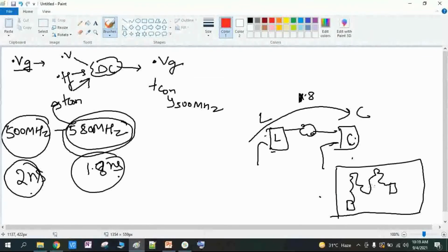What this transition time is, we will discuss later on, but understand the tool tries to improve this net. Think in this way. Let's say to improve this net, the only thing which can improve it is a buffer. I can add a buffer. Right now don't think how it works, that will be taught here. The only thing I'm telling is that to improve the bad feature of this net, I can use a buffer. So for this high detour, I need to use some buffers. Let's say I'm using 4 buffers here. Okay, guys.